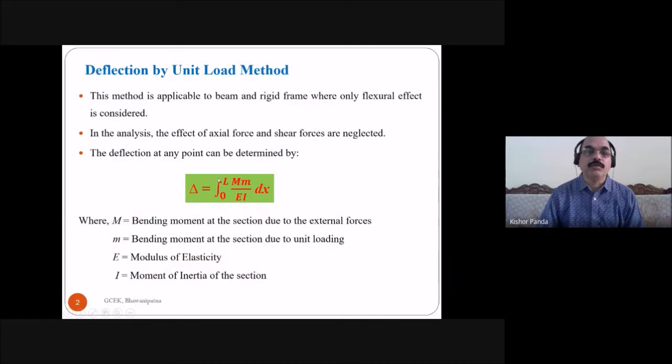Deflection is equal to the integration from 0 to L of capital M small m by EI into dx, where capital M is the bending moment at the section due to external forces, and small m is the bending moment at the section due to unit loading, E is the modulus of elasticity, and I is the moment of inertia of the section.